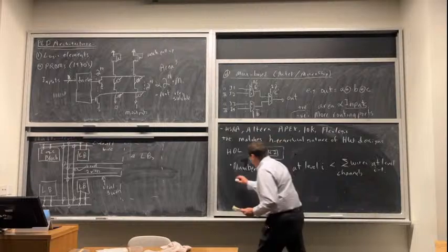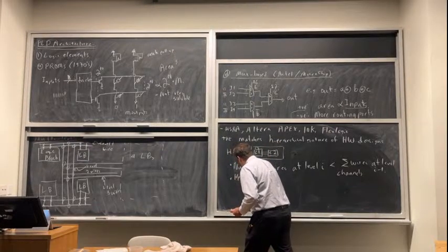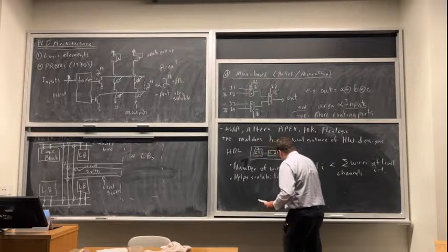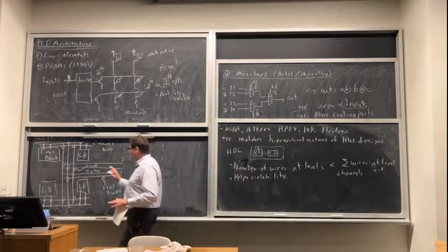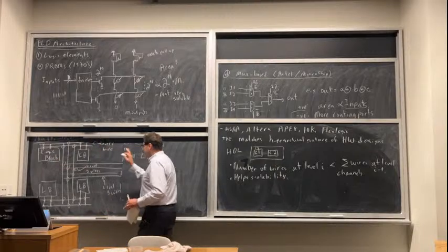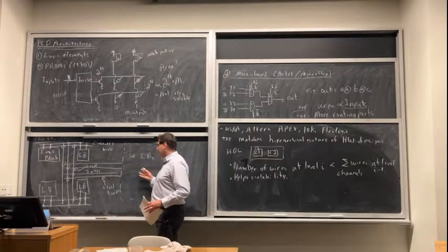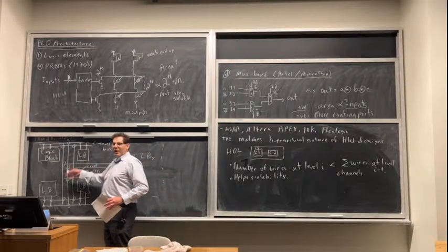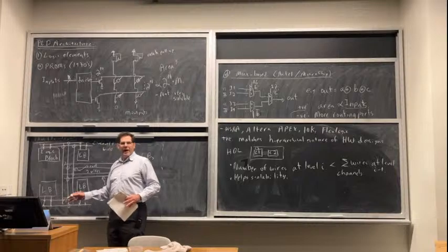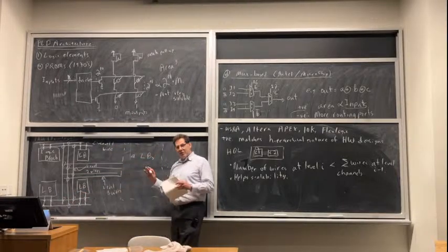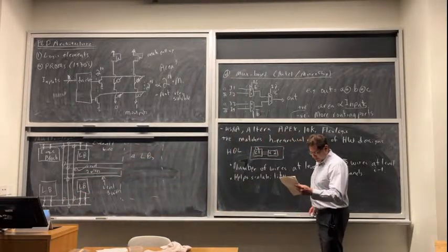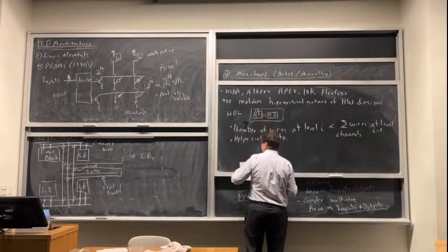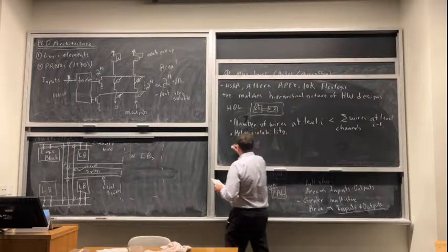Why is that good? It helps scalability. If we want to make a chip twice as big, we have to duplicate everything we had at this level of hierarchy over here, so it's twice as much area. And then we have to add some more. We have to add these wires between them. But the number of wires we add here is less than the sum total of the wires we had in these two blocks. So it means it's going to cost us some, but it's not going to be as bad. Okay, so this can actually be analyzed as well. There's a rule called Rent's rule.